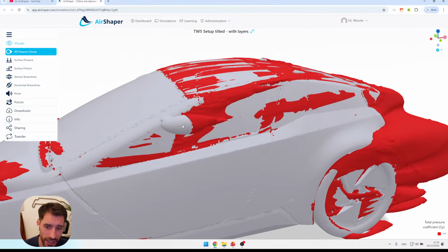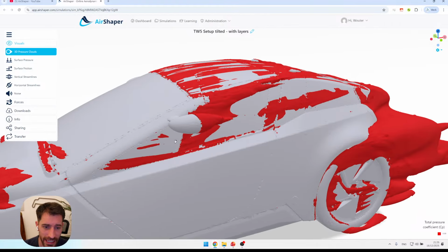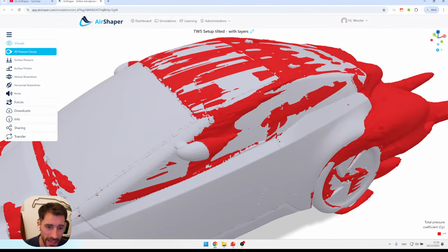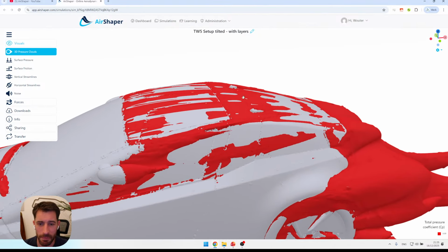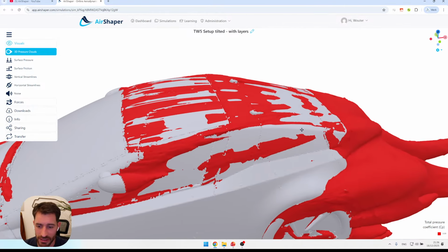Then we saw that we have the B pillars and geometries around the window sticking out. They weren't perfectly flush, so this caused flow disturbances, this one as well. And then we saw that the panel gaps were actually quite large. Sometimes you need these as a rain gutter or something else, but they were quite large, causing mild flow separation in the boundary layer of the car on the roof. And this really disturbed the flow. The hinges were sticking out and so on.